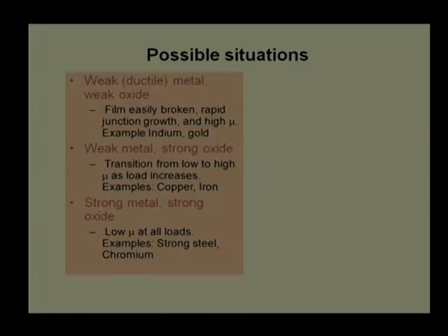In short, adhesion theory, which was derived using junction growth, is applicable along with asperity contact, where the asperities need to be much smaller in size and height as well as in hardness, so that they do not create cavities or a plowing effect on the soft surface. I can think over some possible situations.